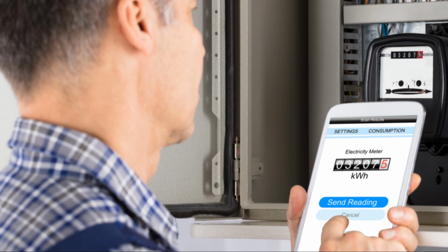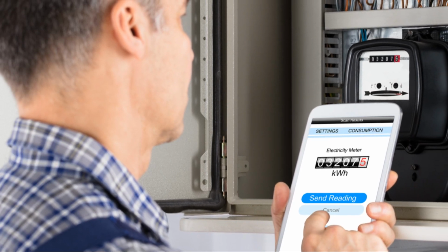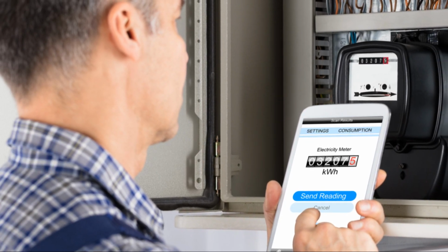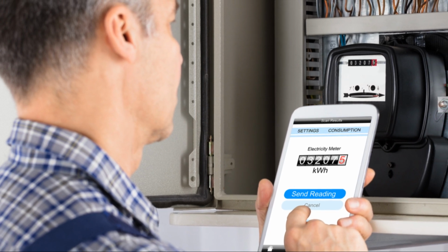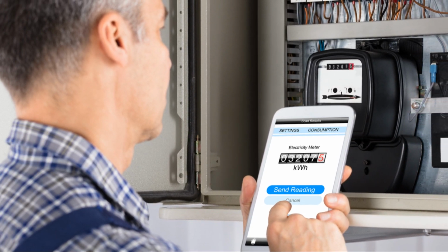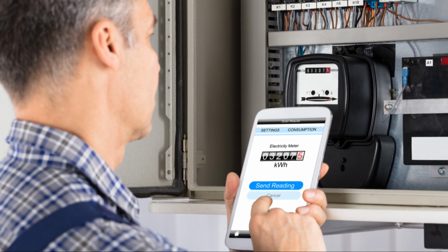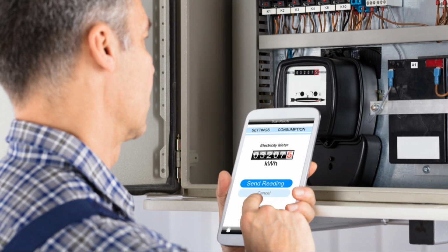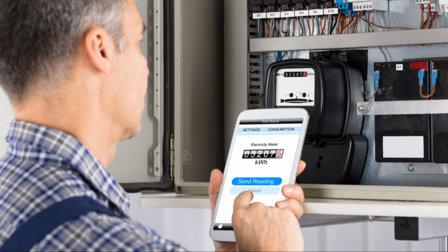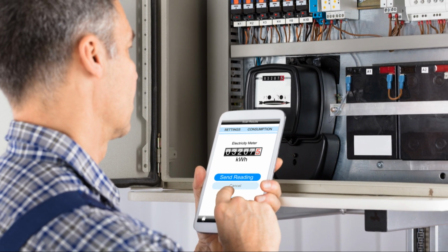Irregular heat in electrical panels, excessive heat in breakers, fuses, or wiring connections, is a strong indicator of electrical resistance, often caused by loose connections, corrosion, or circuit overloading. These heat anomalies can lead to voltage drops, energy loss, and potential fire hazards if not addressed. Regular thermal inspections help identify these issues early, allowing for preventive maintenance to enhance electrical system reliability and safety.